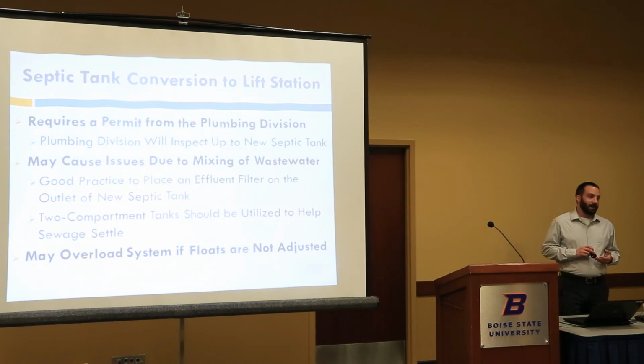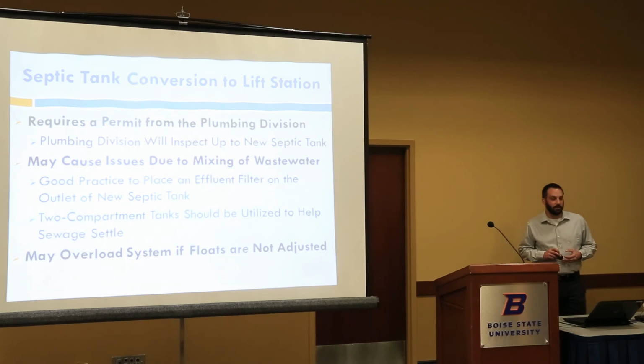So if you can't do that, I know that sometimes those tanks are hard to find that have those deep bury depths approved for them, or the cost may drive the property owner into wanting to just convert to a lift station. Know that when you do that, you are mixing up that wastewater. You're grinding everything up and sucking it out and pushing it out into the new septic tank. You're not going to get the same settling that you did when all that wastewater entered the septic tank under gravity flow from the house.